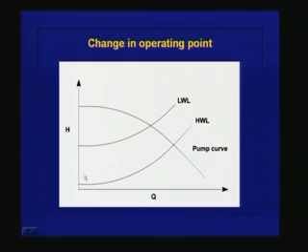The pump efficiency curve, we have seen the efficiency varies with the discharge and depending upon the specific speed of the pump. Now the pump should be selected or should be designed, or we should take such a pump such that the efficiency versus discharge curve, let us say this is the efficiency versus discharge curve, that efficiency is more or less maximum between the low water level and high water level, and that efficiency curve is more or less flat between these 2 points. That is a very important point in the selection of the pumps.